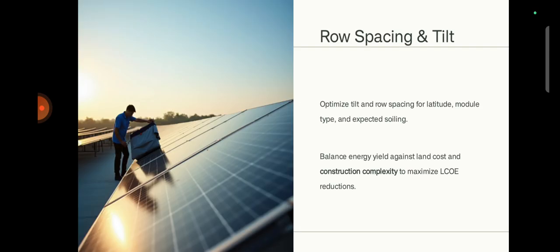Layout optimization, row spacing, and tilt. Optimize tilt and row spacing for altitude, module type, and expected soiling.